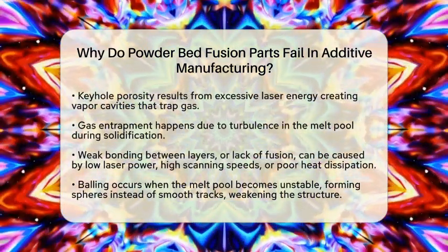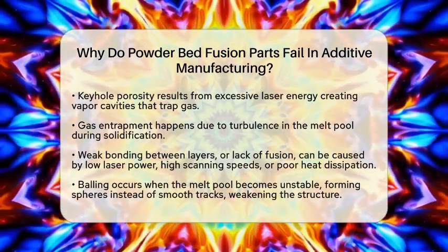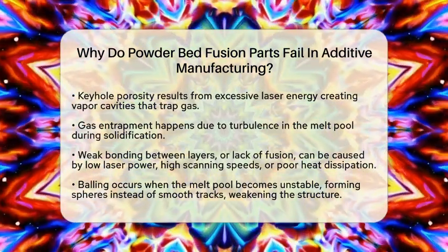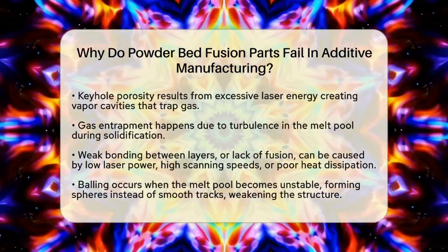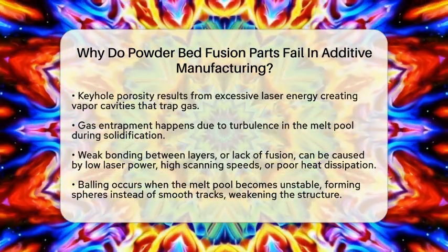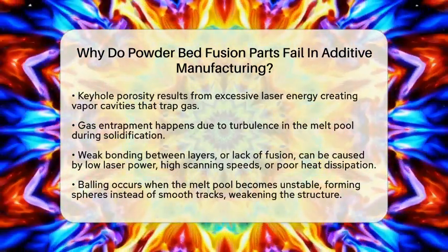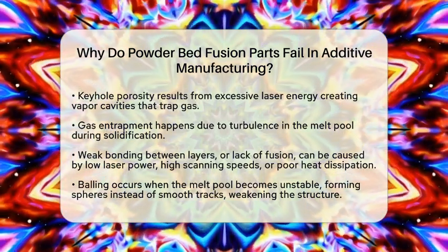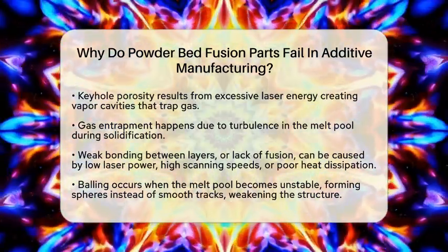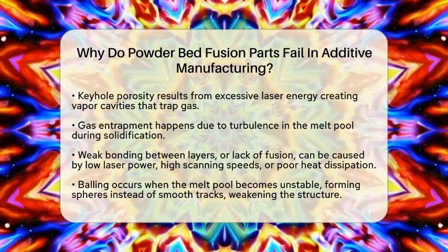Keyhole porosity is caused by too much laser energy creating vapor cavities that trap gas bubbles. Gas entrapment porosity results from turbulence in the melt pool, trapping gases as the material cools. These tiny holes act like stress concentrators, making the part more likely to break during use.